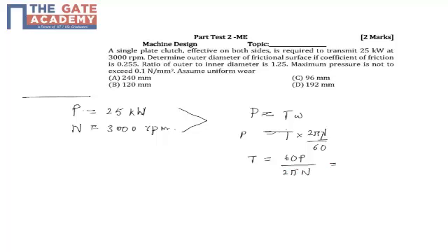Here 60 P is based on 25 kilowatt, and n is 3000 rpm. We get torque to be 79600 Newton mm. Basically in meters we get 79.6, and then we convert into mm because we want ultimately the answer to be in mm. So this is the torque.